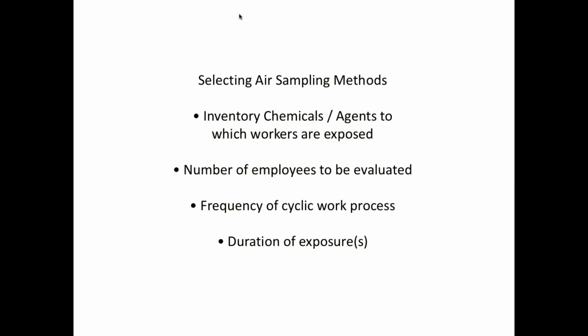Okay, so sampling methods: you want to inventory the chemicals and decide what the exposure is, so you know what procedure to use. You want to figure out what the work process is, so you know when the significant exposures take place. You want to know how long the exposures are, and you want to identify the employees that might be exposed.